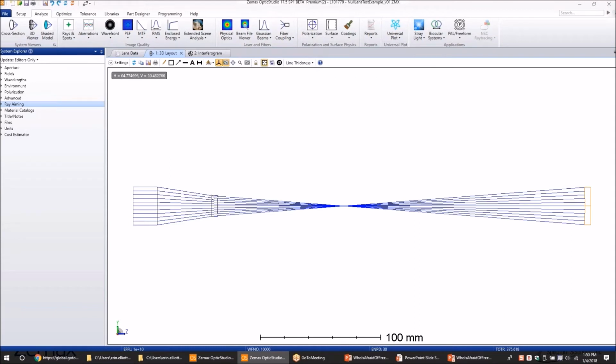So for the CGH, you can create a nice wavefront that matches your part, and the maximum slope that you can tolerate on your freeform part is then limited by the resolution at which you can write the CGH here. You need 2 pixels of a CGH under any given slope, so that you get Nyquist sampling of your wavefront.